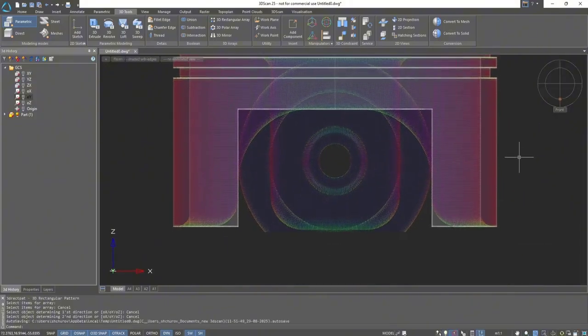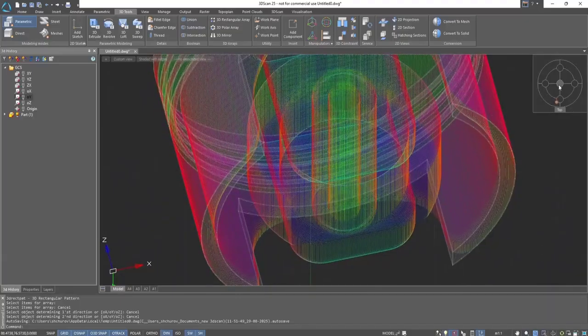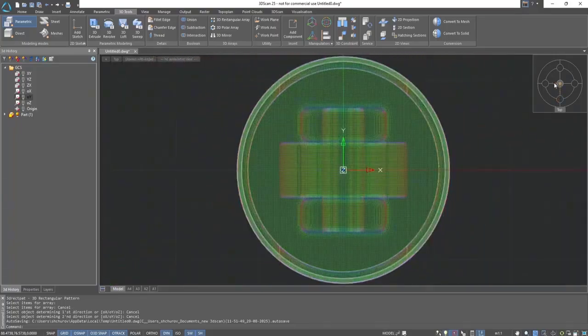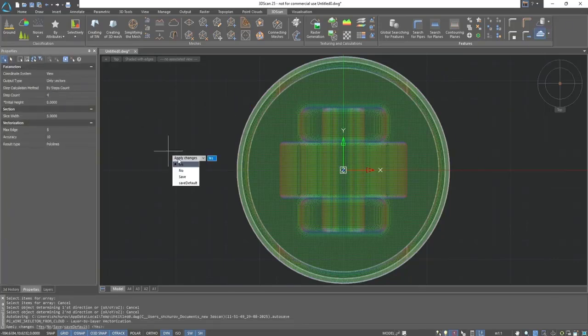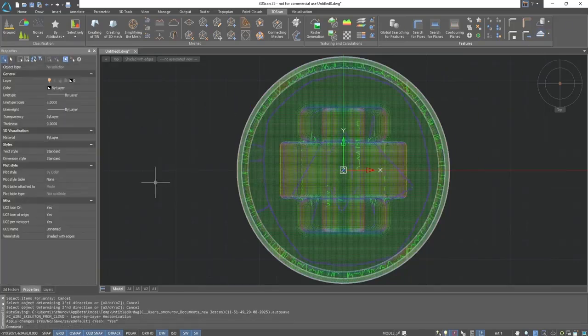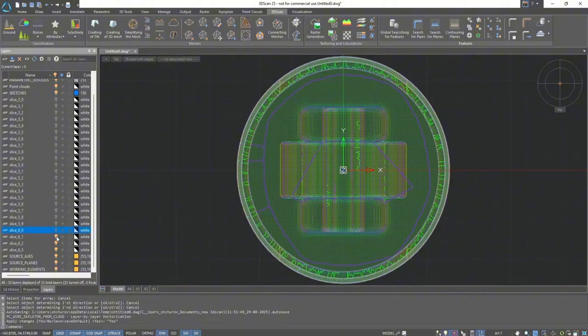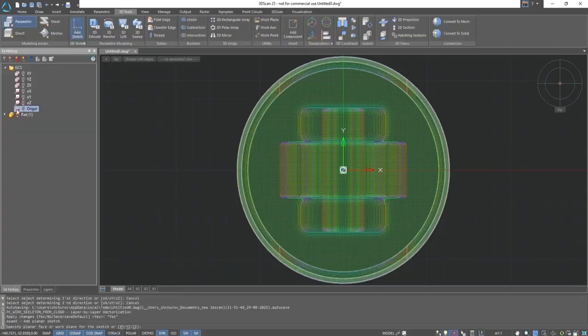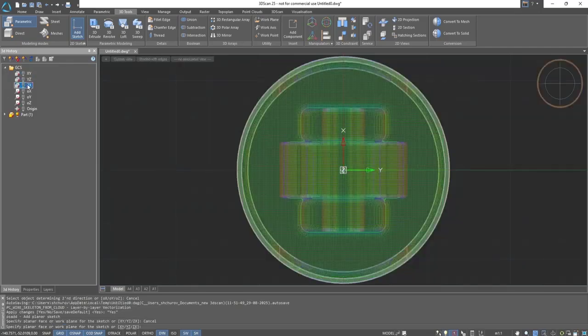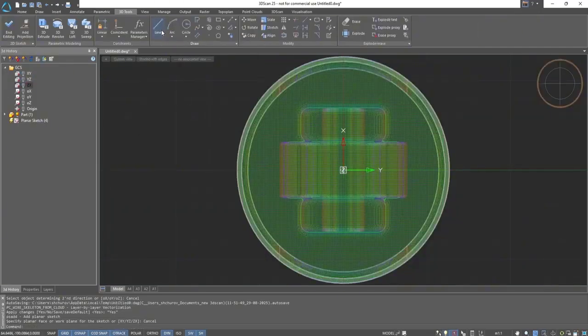Now there's one more important thing left: create two elements where the piston pin will be inserted and the connecting rod will be fixed. Let's create 4 more sections. Choose top view to build the contour of this part of the piston. Let's leave only the layer that most clearly describes the geometry we need enabled. Then add a new sketch associatively to the upper contour of the piston. Now you can create a sketch in a similar way and then clip it.